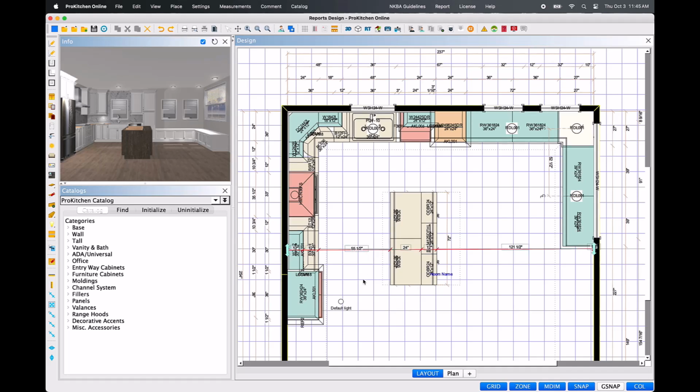If you need to know a particular angle in which cabinets or items are placed in relation to one another, you will need to utilize the Angular tool. Navigate to the left toolbar. Left-click the angular icon to grab the tool. Drag the mouse to the plan view. Hover over the edge of the first item, and left-click when the purple line displays. Then drag the mouse to the edge of the second item, and left-click once more when the additional purple line appears to create the dimension.